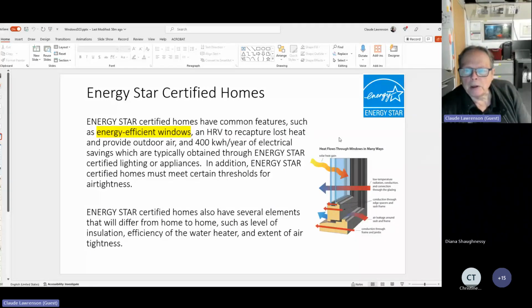When we think about windows and doors, I call them energy holes, because that's where we're going to get the most significant amount of heat loss, particularly in the heating season, transferring from the inside to the outside. So when we talk about the building science portion, heat travels from the warmer side and wants to move towards the colder outer side.